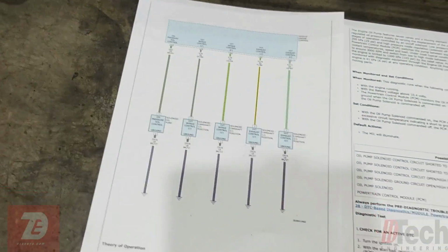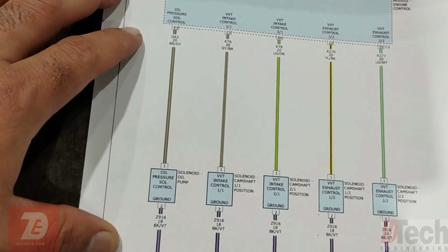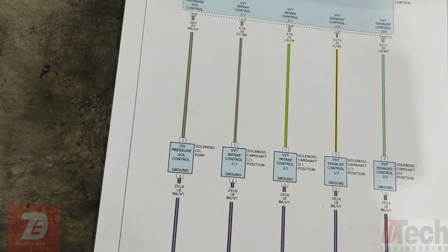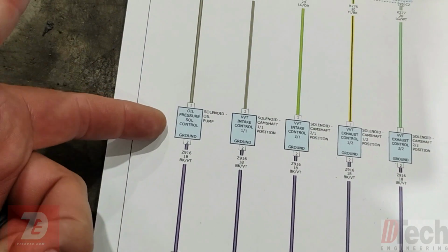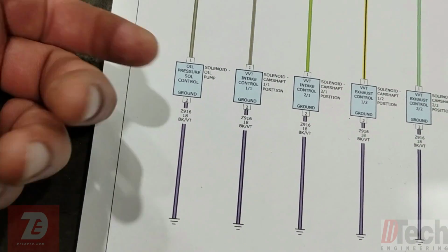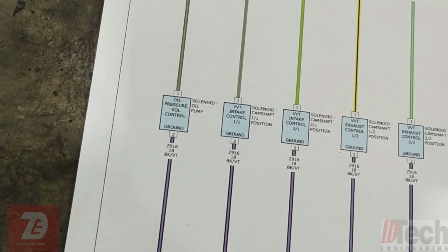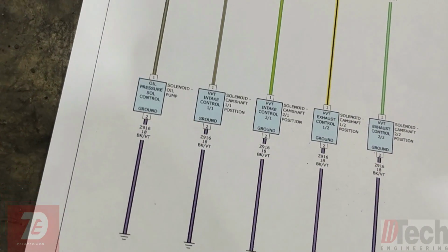Honestly, it almost reminds me of the old school Honda VTEC systems. It's a two-stage cam, a high cam, a low cam, and it's controlled by an oil control solenoid valve. Based off of RPM, it'll want low pressure, and above a certain RPM, it'll want high pressure.